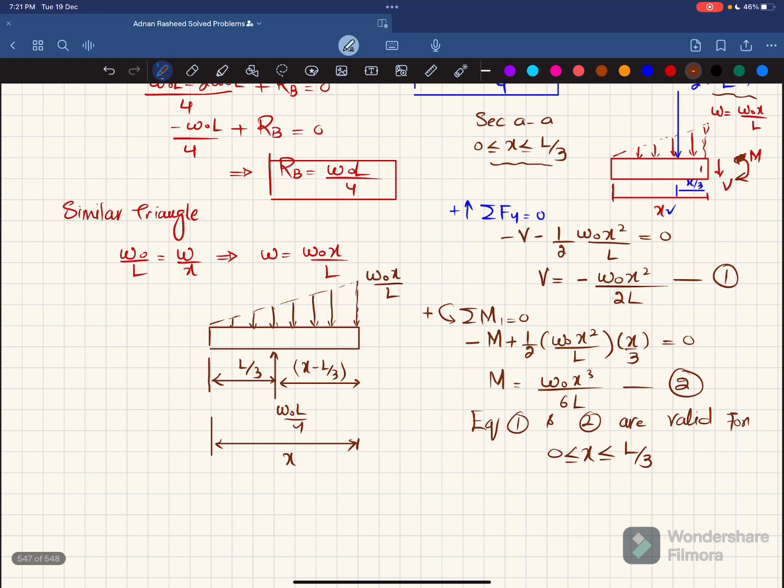So when you cut it, you will have a shear force like this, and you will have a moment that will be counterclockwise. Why? Because you can see now you have this force and this force as well. So we have taken it counterclockwise because its effect will give you a positive moment. Okay, so this is your point 2 because it is the section at point 2.